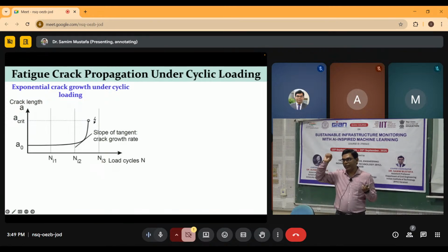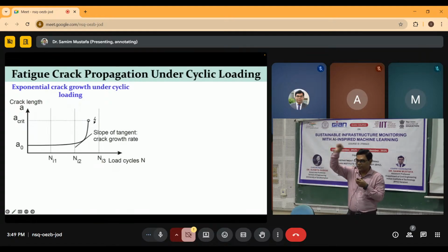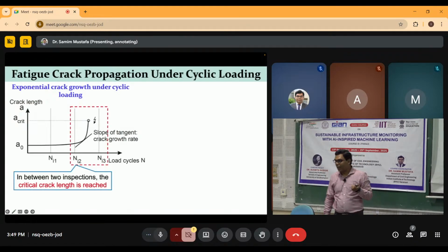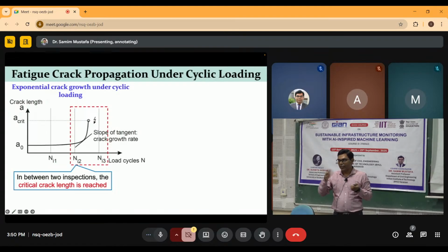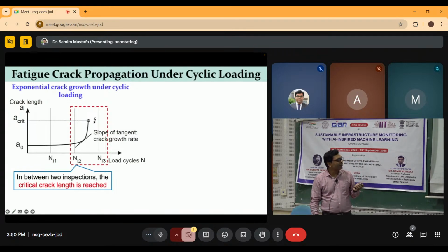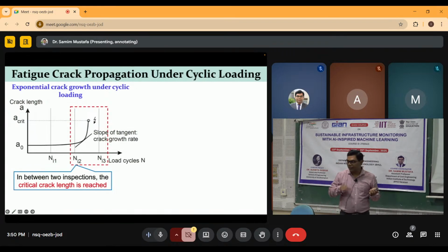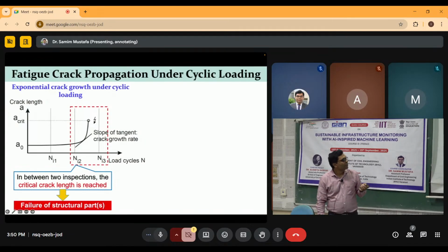So initially you will see there is a hair-like crack, a very minute crack. Then you are not able to see it, as fatigue cracks are penetrating in nature. Penetrating means it is going inside the member, through the thickness, okay. So that is the dangerous part of fatigue damage, compared to other damage like corrosion. You can see corrosion is visible at the top layer, the member has been corroded, okay. But in case of fatigue it is very difficult to detect, and the penetration is very difficult to measure unless you have a laser light scanning system, okay. Otherwise you cannot detect.